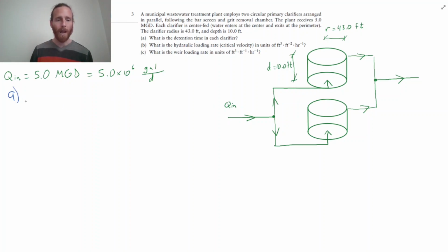So the detention time, we often write that as theta. That's simply equal to volume over flow. And so this will give us a unit of time. The detention time is a measure of how long the average water particle spends inside the system. So depending on the size, that could be from seconds to days. You can measure this for the Great Lakes and it can be years.